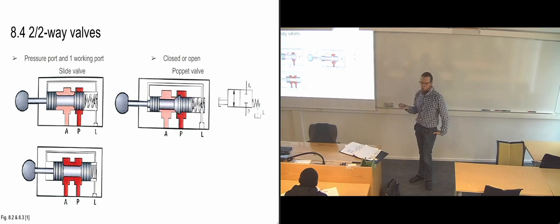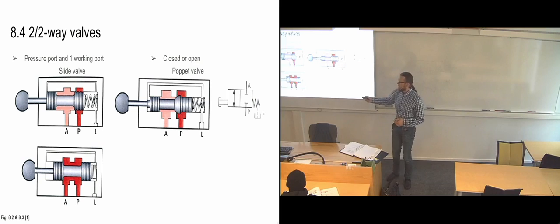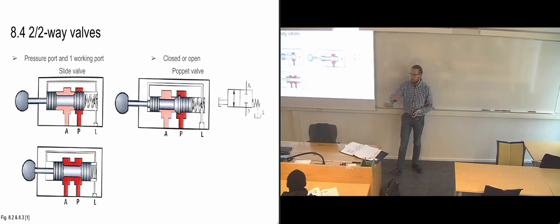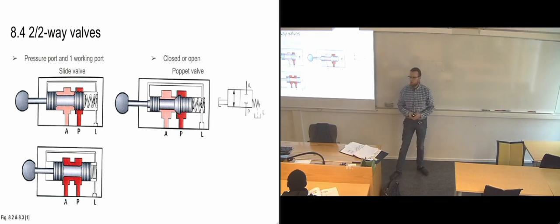So depending on if you have an old valve that's been subjected to wear and tear, maybe you have more than usual leakage behind the piston here. You might find that once you release the valve, the lever moves outwards, then really slows down and moves the last part very slowly, because it's trapping quite a lot of leakage oil and needs to push it through the leakage line. So it's going to take a little while to evacuate all of that leakage oil.